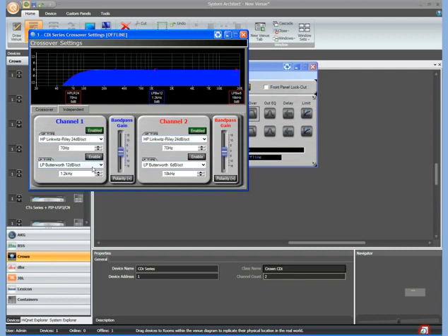So the first thing that I will do is set a low-pass filter. I'm going to come in here and type in 100 Hertz. I will turn on this roll-off on the low end just in case to keep the transformer or the woofer itself from being overdriven at extreme low frequencies. But I'm going to set it at 30 Hertz.